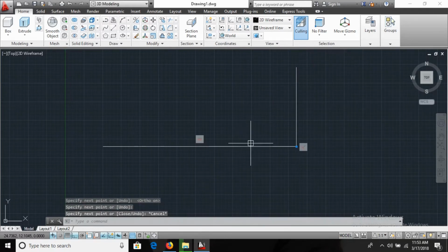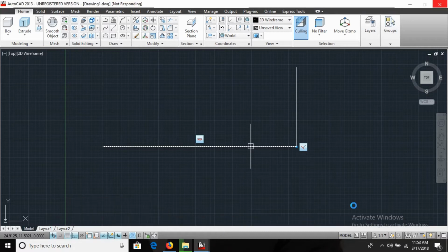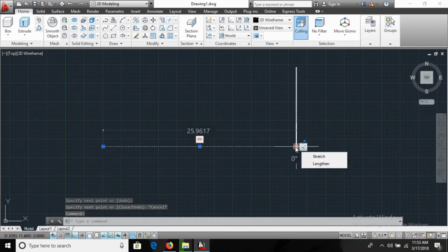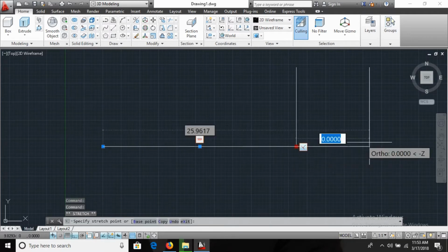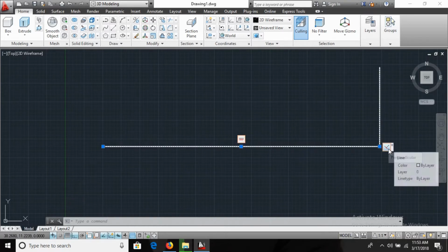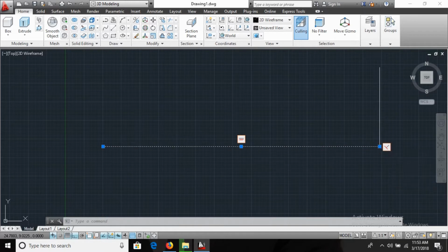See, friends, if I increase this line on this side, automatically this other line also follows. This line will automatically follow when you are increasing this particular line. So I'm selecting this line, and by using this grip we can extend this side. Automatically this line segment also follows. And here we can observe, friends, these things are called the constraints.